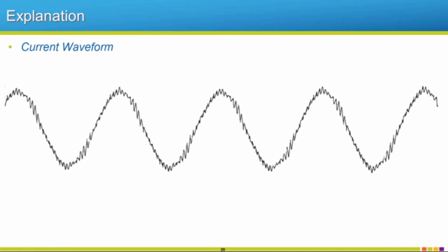You got to remember, if you're switching these IGBTs a lot more often, what happens? Excess heat's going to happen. So these IGBTs are going to heat up quicker. So you may have to deal with a derate, especially if you're loading this up to its full capacity. There's built-in safeties that will protect the drive, but you're definitely firing those IGBTs more, which is going to create more heat. Hey, it makes a nicer waveform, but you got to deal with that. So a lot of your commercial applications like this higher carrier frequency because they don't like to hear the motor upstairs.